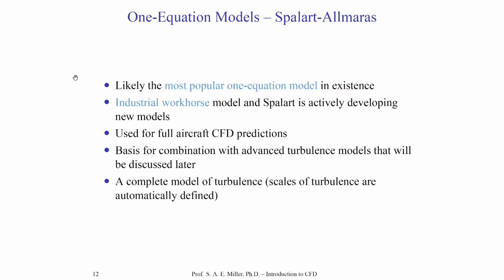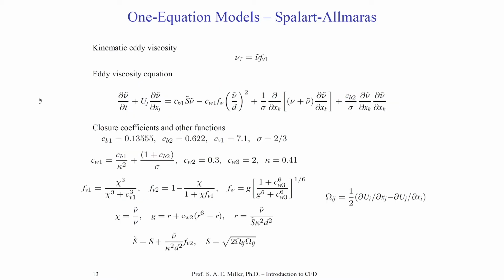Now, Baldwin and Barth tracked the turbulent Reynolds number. Prandtl-type models, for one equation, tracked turbulent kinetic energy. The brilliance of the Spalart-Allmaras model is they developed a single partial differential equation that tracks eddy viscosity. And here you can see it in the familiar form. Here we have a partial derivative of the eddy viscosity, written with a tilde, with respect to time, plus u_j times the partial of the eddy viscosity with respect to x_j, equals all the terms on the right.